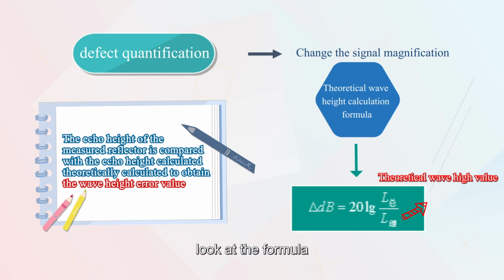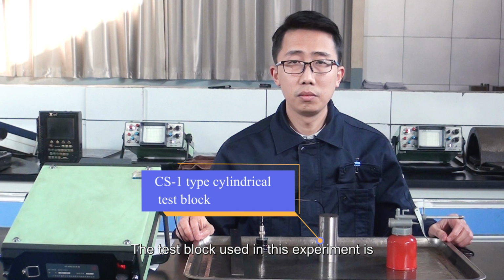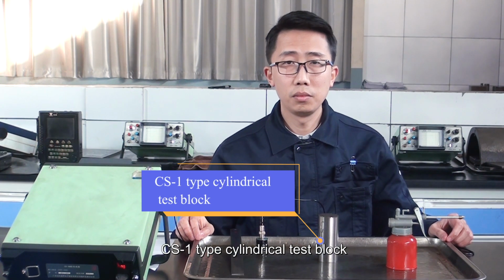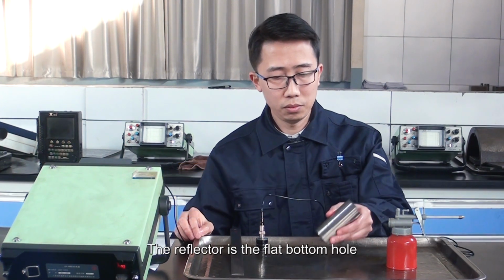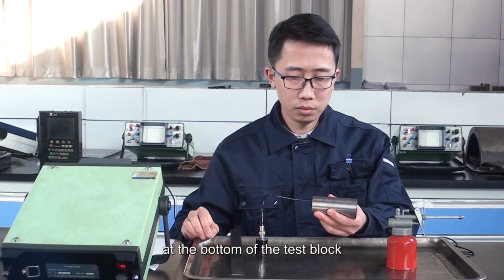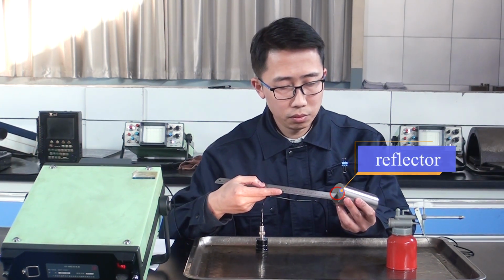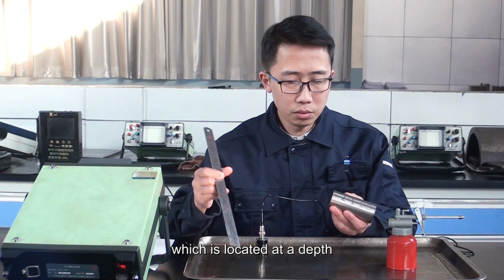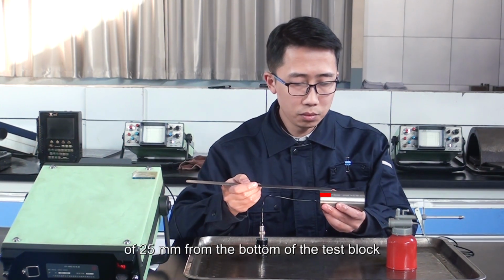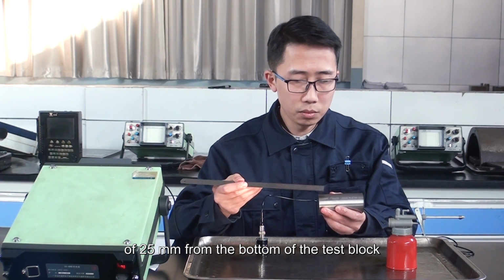Look at the formula. The test block used in this experiment is the CS1 type cylindrical test block. The reflector is the flat bottom hole at the bottom of the test block, which is located at a depth of 25 mm from the top of the test block.